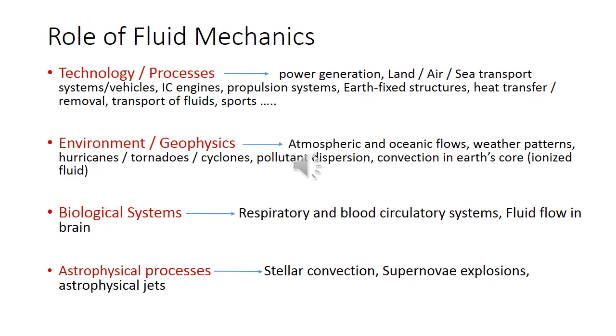Moving on to internal combustion engines that you normally have for your automobiles, your bikes, any kind of fossil fuel driven land transport vehicle. So IC engines, what is the role of fluid mechanics there? In these engines, there are a lot of processes, gas exchange processes, intake and exhaust, and then inside the cylinders you have mixing and charge motion, and apart from combustion, which is also a fluid flow process, but probably a lesser role of fluid mechanics there. But in the gas exchange processes and mixing inside the engine cylinders or the manifolds and things like that, the fluid mechanics play a very vital role.